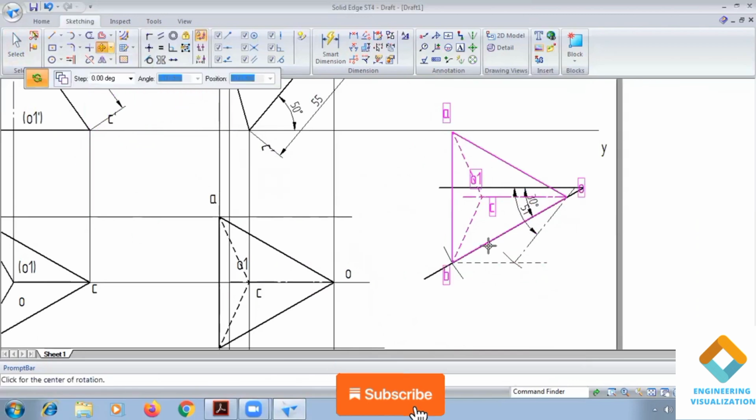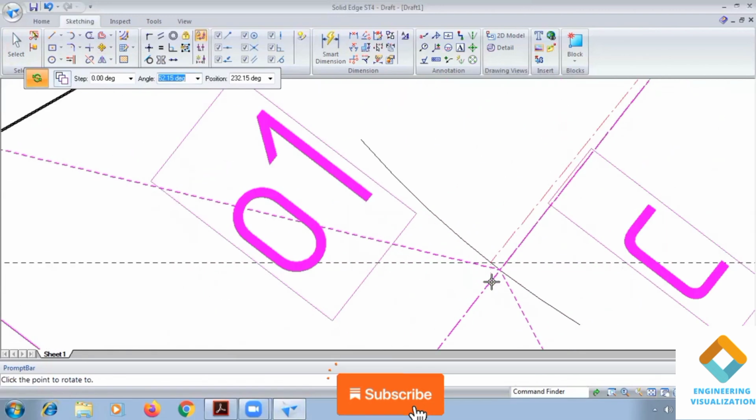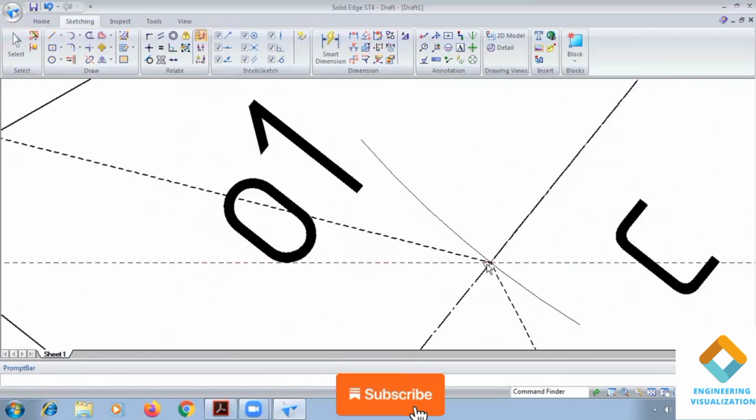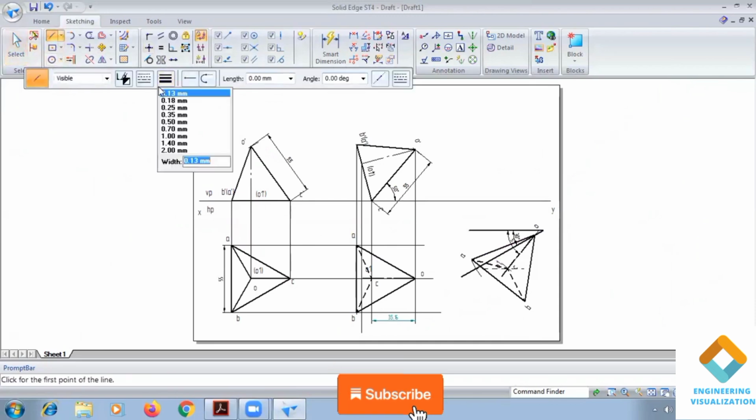So using move command we have copied. Take the reference point of OC and place it on the angle line here. So place it pinpoint. You can zoom in when you're placing it. Okay, so now draw the projection lines to complete the final position here.